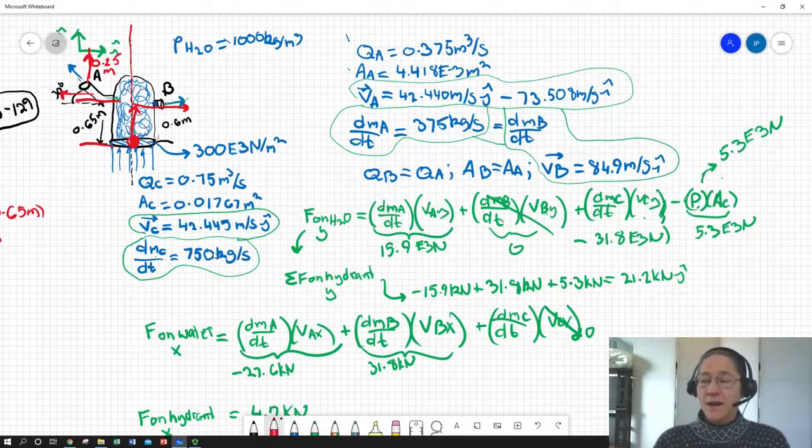And then that new momentum, of course, is granted via our impulse per unit time given by the mass flow rate, and boom, you have your force. So all you really need to do is know the mass flow rate at each orifice, the velocity change to go from stagnant inside the vessel to whatever the velocity is when it's shooting out of the vessel, which you can get again from the flow rate and the orifice diameter and the density of water. You have everything you need to know for localized application of forces.